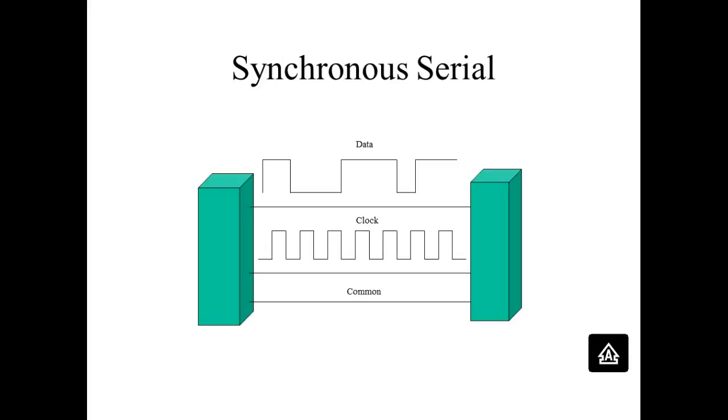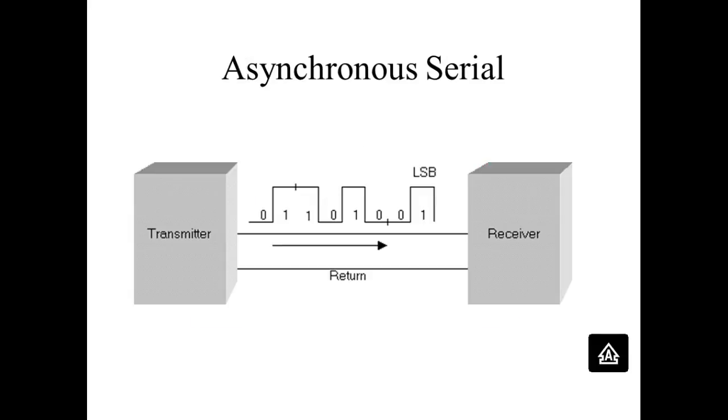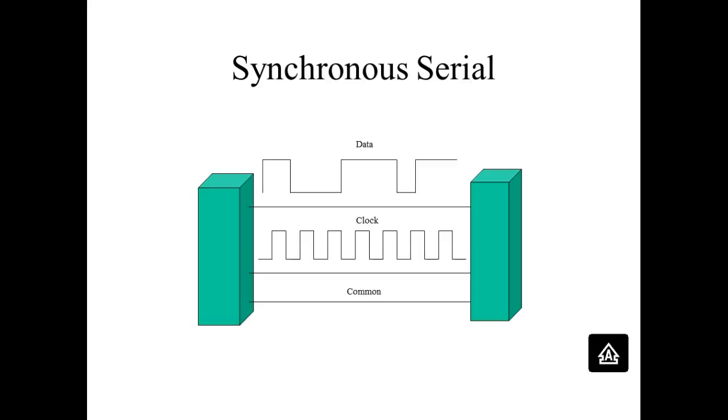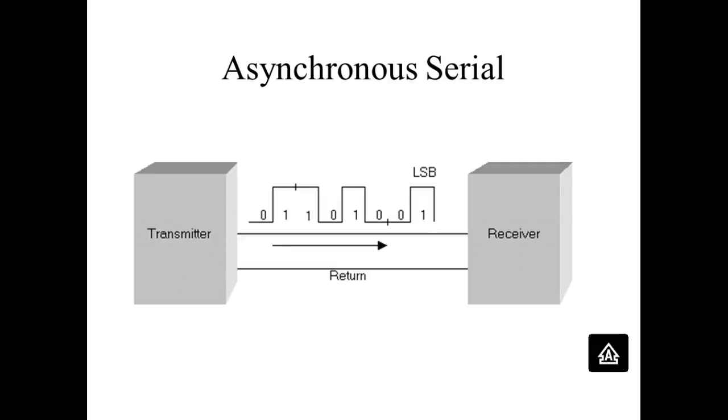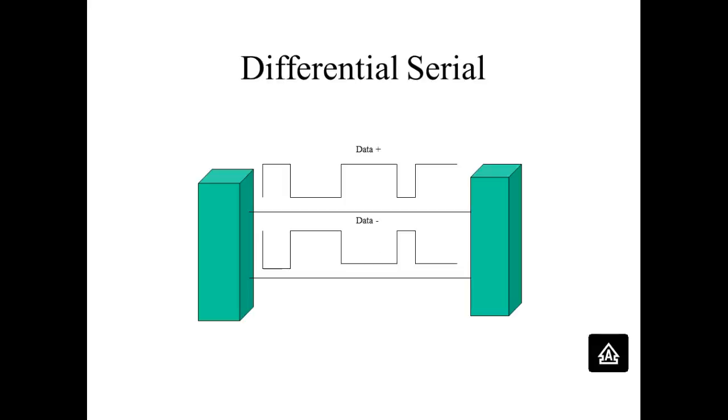Digital serial link. We talked about synchronous serial, asynchronous serial. You okay? What's the advantage of synchronous serial? Well, it's timed. It's synchronous, right? It would be the fastest we could send data. What's the advantage of the asynchronous, which is what most stuff is in? It's a lot cheaper. Saves a lot of wires. Saves a lot of electronics too.